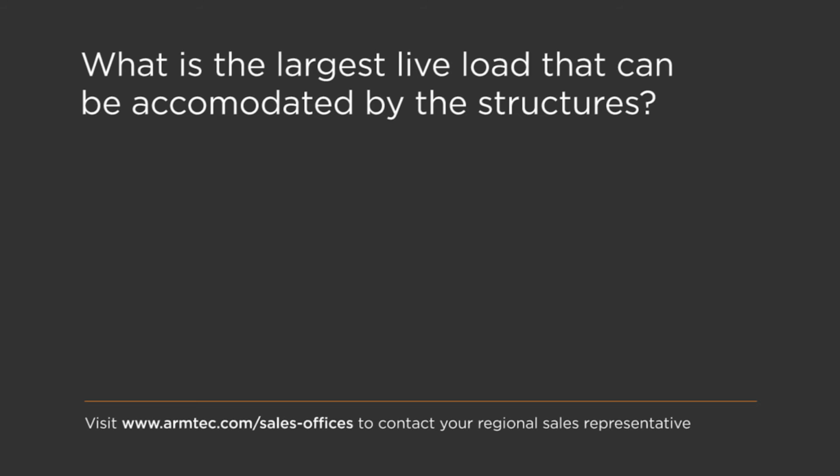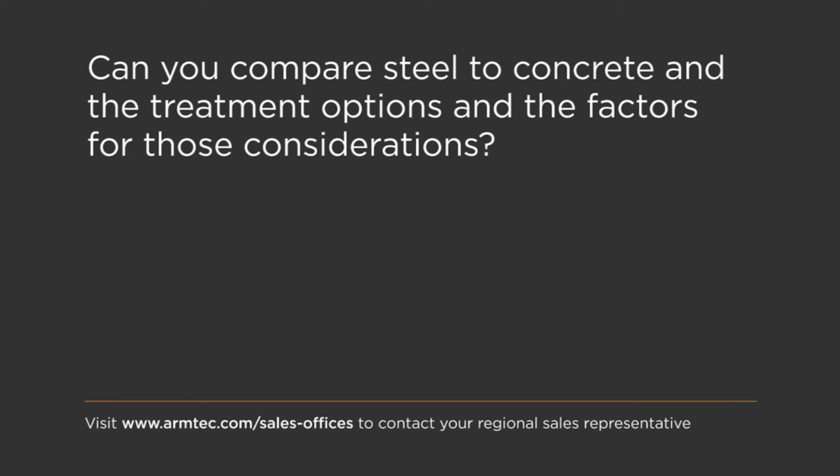Excellent. And this one did come in before the session, and you did spend quite a bit of time comparing them, but we might as well just do a quick summary. Can you compare steel to concrete and treatment options and the factors for those considerations? Yeah, for sure. Those are considerations that are addressed in the AASHTO standards. There are usually corrosion criteria for any steel facing systems. So those are typically the design considerations. Obviously, when we're talking about roadway applications or highways, there are always salting considerations and potentially corrosive conditions for a steel system. In those cases, concrete can definitely be an option that will provide a longer service life than potentially a steel-faced retaining wall.